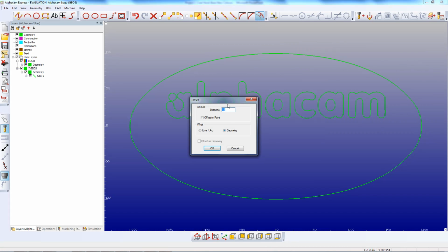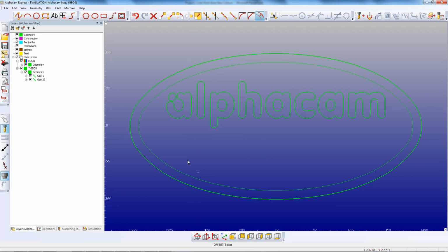So we'll start by selecting offset under edit. I want to offset the whole of that geometry by 12mm. I only want the bottom half, so I'm going to create myself a line using F6 again, the endpoint of. This line I'm going to use as my cutting geometries. Under trim, select cutting geometries, and the bit I want to delete. I can now also then come back and select delete and remove that line.